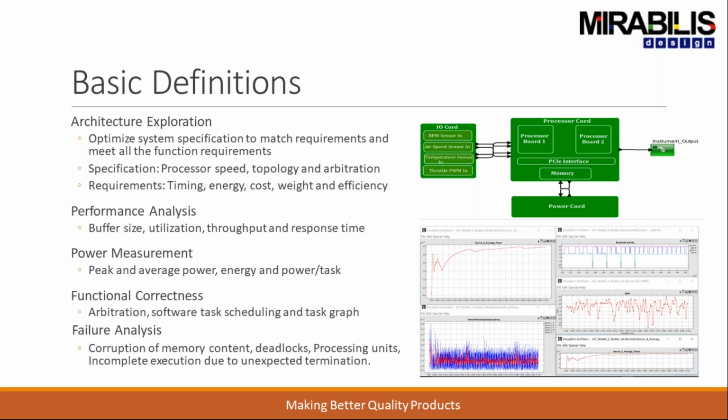The key term architecture exploration means that the specification that has been done on paper, PowerPoint, or Excel can be assembled and represented as a model, as you can see on the right side, and then run a variety of simulations by varying the speeds, changing the algorithms, arbitration, and evaluate the timing, latency, etc. to come up with an optimal solution.